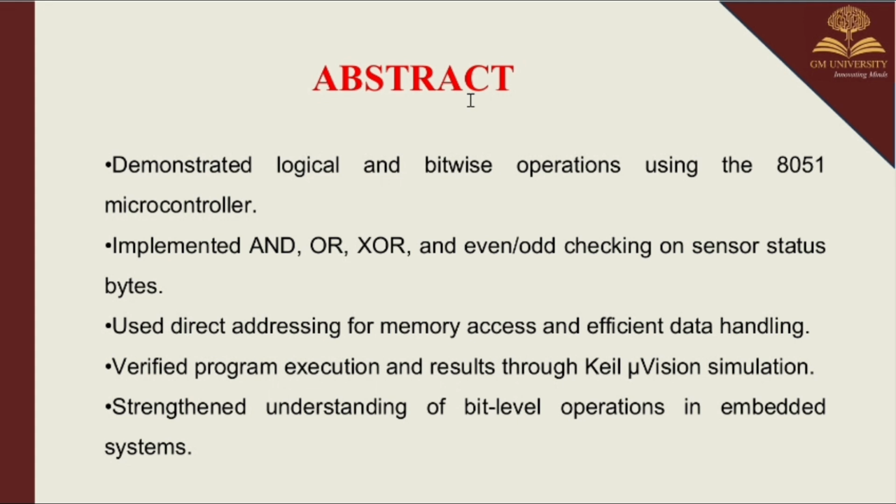This will demonstrate the logical and bitwise operations using the 8051 microcontroller. It implements AND, OR, XOR, and even NOT checking on sensor status bytes, utilizing direct addressing for efficient memory access and data handling. The program execution and results were verified through Keil MicroVision simulation, strengthening the understanding of bit-level operations in embedded systems.